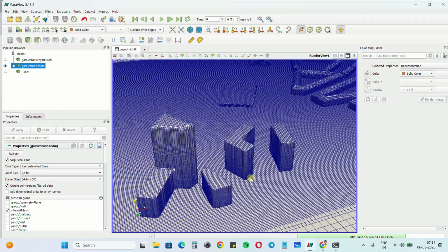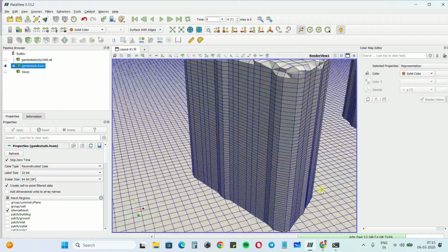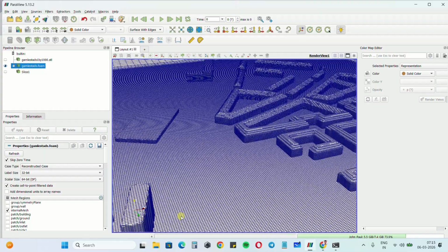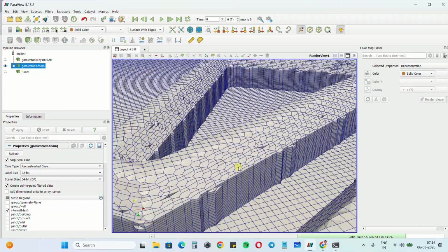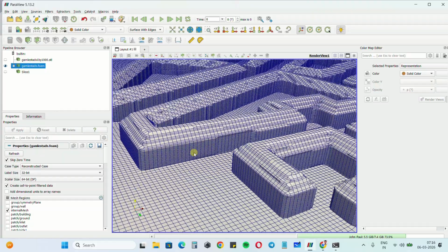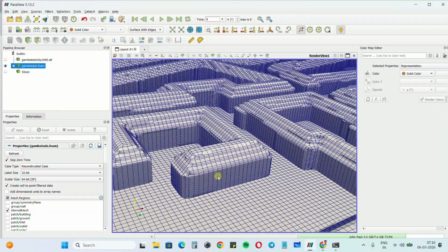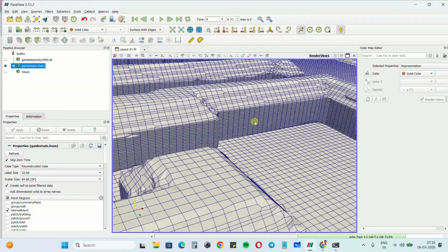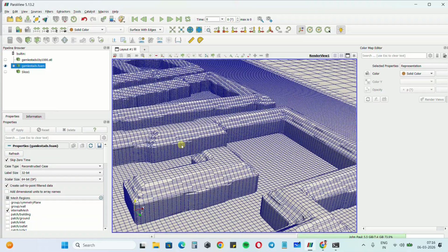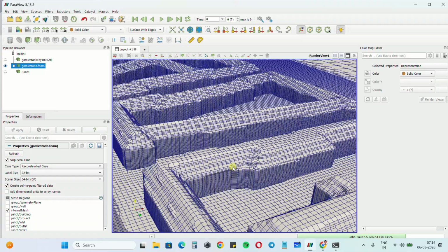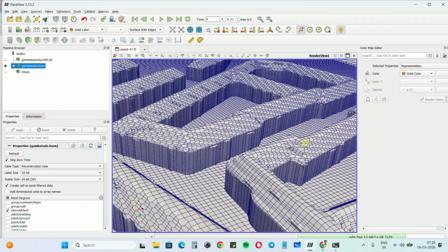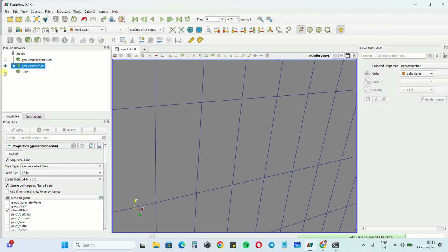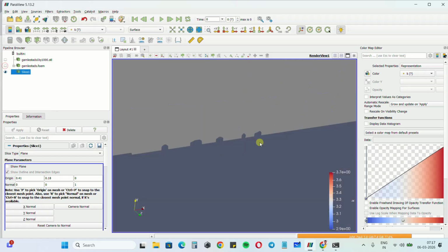You have all the buildings, especially the lateral surfaces that concern us the most, sufficiently refined. You have to iterate a bit on the snapping settings in order to get a final okay mesh. So this looks fine to me. What I'm concerned with most is the lateral surfaces of the building rather than the chamfer at the roof. However, even if you have some cells failing at the roof chamfer, that will also affect the result. So if you have an okay for the mesh, then it's fine. If we again observe the slice, the warning is okay.